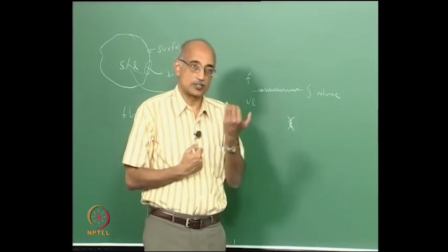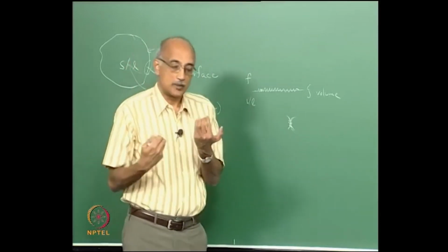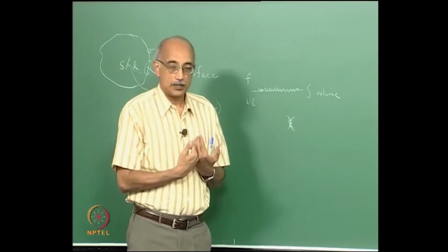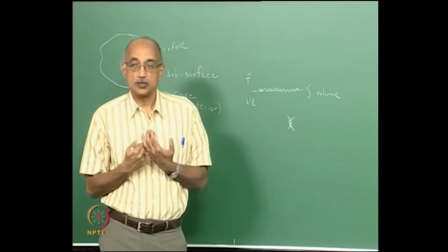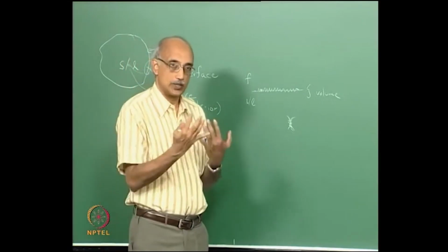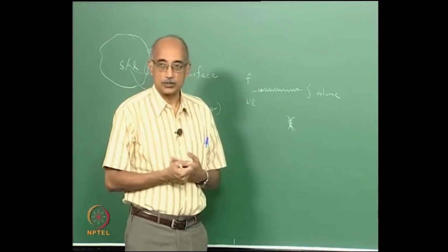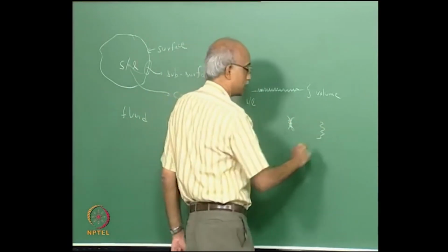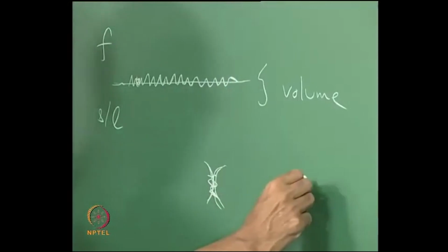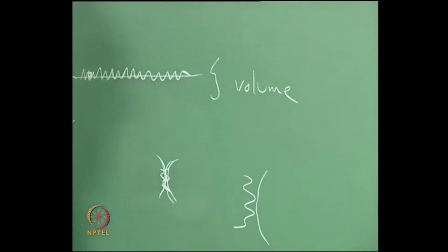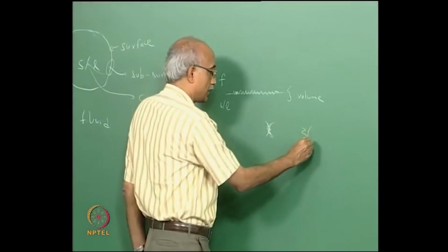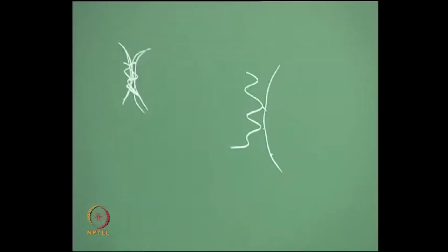On the other hand, if you have a smooth particle coming in contact with a particle that is relatively rougher, the contact area can actually be significantly reduced, and therefore the interparticle adhesion forces will also be reduced. Think of it this way: if you have one particle that has a profile like this and relatively the other particle has a profile like this, then the contact areas are very isolated, right? They are making contact only at these locations.